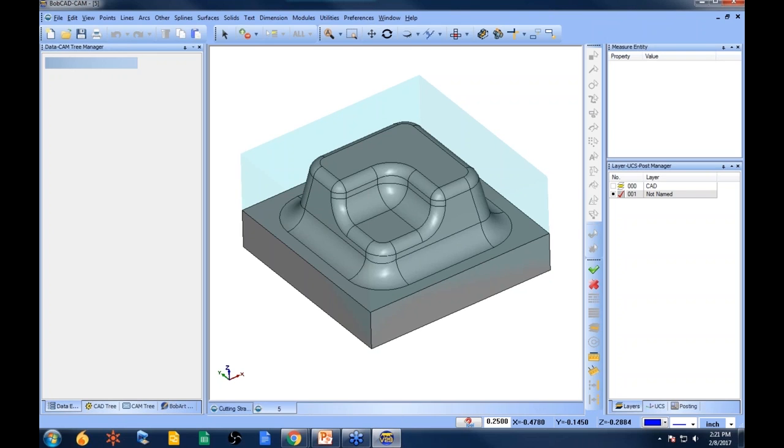You generally get an overlap is how you attack it, by using top and bottom of job. If you don't mind me asking, Steve, what version are you running? Is it 29? Because there are some changes we made to the trimmer that deal with angle ranges. So you may want to just email me the file, al@bobcad.com, and I'll see what I can do to show you different ways that you can attack it.